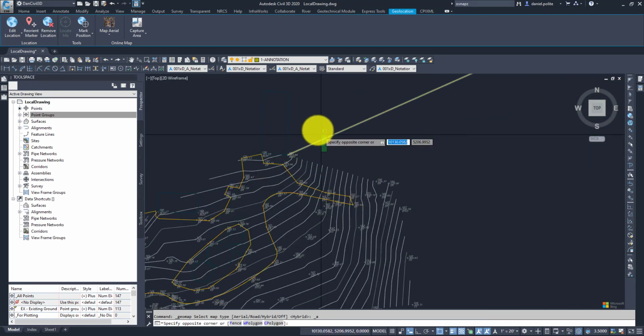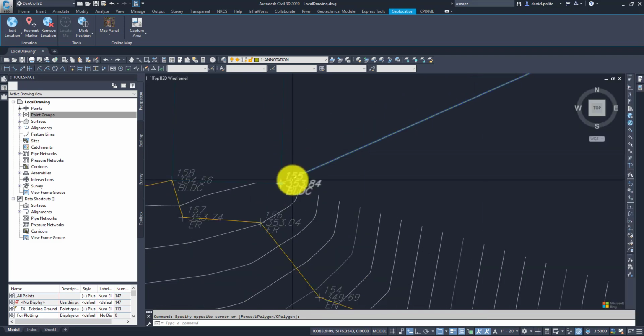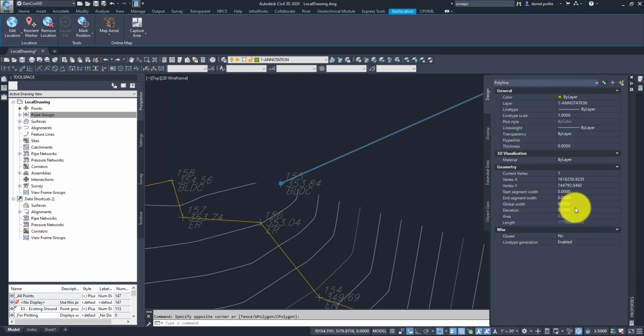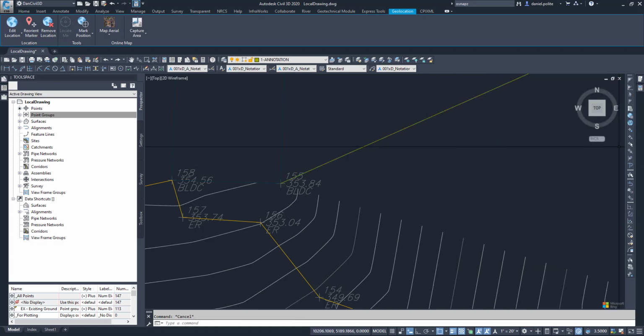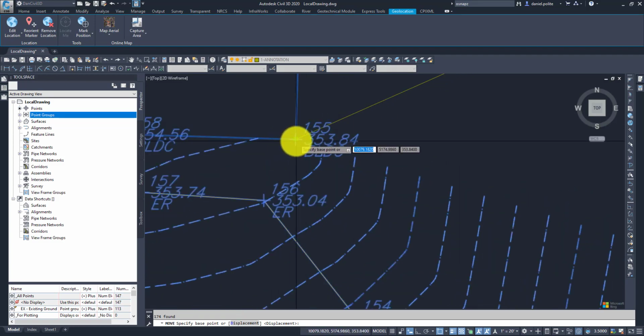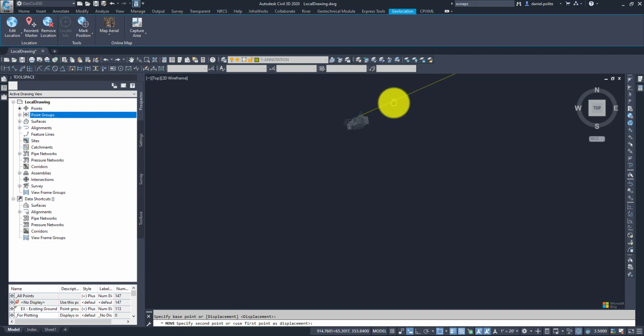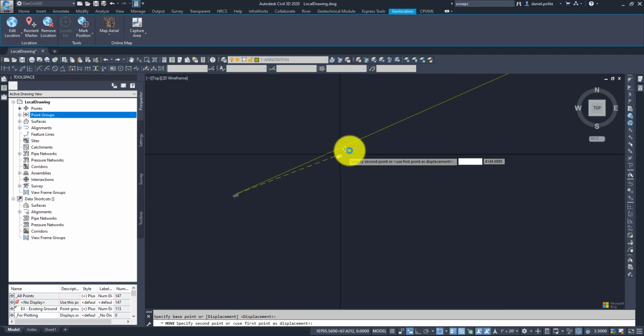Again, right now, you have that polyline set as a 0 elevation. So in this example, we want to change that to 353.84. So long as you have that selected, you can change it to 353.84. And just make sure that you don't select your polyline, but you're selecting everything. And then you're just going to type in MOVE for move. You're going to select this specific building corner point. And again, you zoom out and just follow along this polyline.